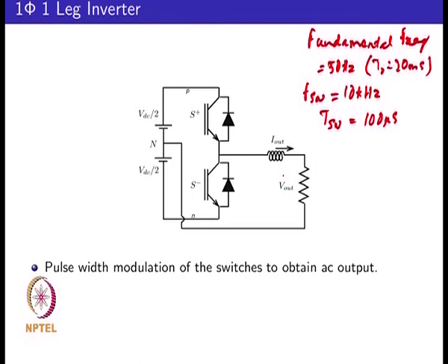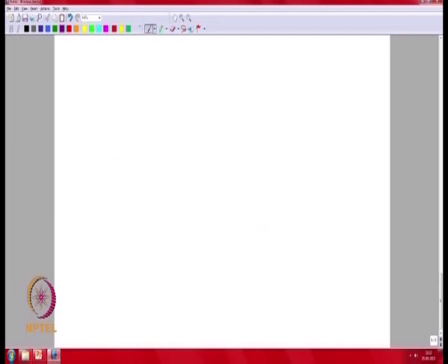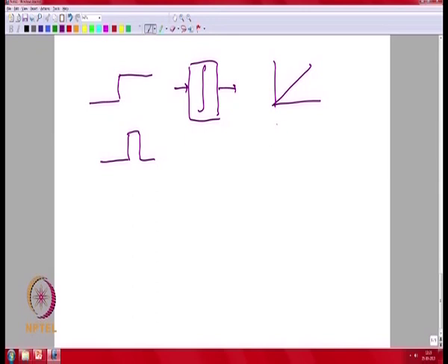So, if you look at essentially the filtering effect because of an inductor, if you look at the input to be a step waveform going through an integrator, which might represent an inductor or a capacitor or some electromechanical time constants in a motor type of system, the output is essentially going to be a ramp when you are having a step input. If you are having say a pulsed input, essentially you will have something which steps up and stays flat as you proceed through the filtering circuit.